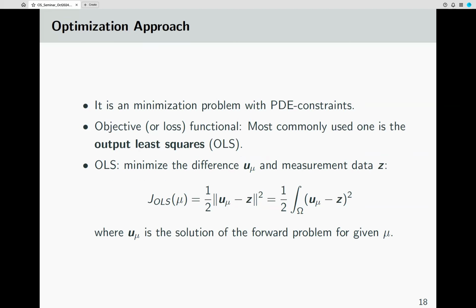So how do you solve an inverse problem? You basically have to make it an optimization problem. Here, this z is our data, the displacement vector function measured at certain locations in your domain. So it's discrete. Now we need to find a mu, the stiffness parameter, for which the corresponding displacements are a really good match for this measured data. You're basically trying to make this difference minimal. So you find the mu in a way that the corresponding displacements, for which we have to solve the direct problem, match the data that we have very well.